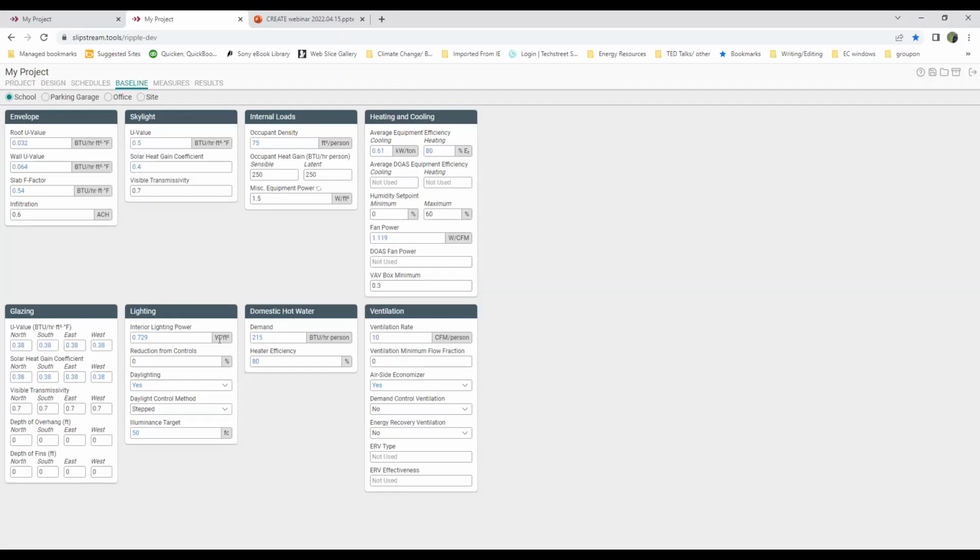So going around the space, calculating the number of fixtures, looking at the watt per fixture, so that you have the total watts multiplied by the number of fixtures, and then you calculate the watts per square foot based on what area of the building is lit. And then thinking about if it is an older lighting fixture, what would a LED retrofit do to the space? Because if a CFL is about 60 watts, the LED is going to be about 5 watts, if that. So what would that mean if 100 CFLs are replaced with 100 LEDs? What's the energy impact of that? So that's something that they can visually assess and bring it back to the tool and do the computations.